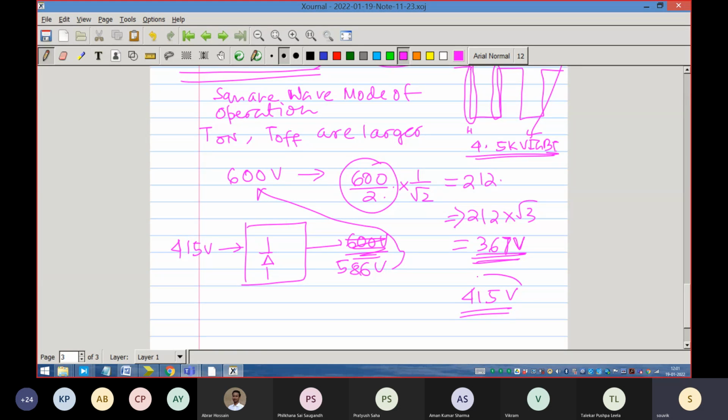But the machine is designed for 415 volt. So you are underutilizing the machine. You are not able to apply 415 volt to the machine. The machine is underfluxed because that is what you are able to do. So there is a natural tendency to increase the voltage and go to 415 volt. When you multiply by another factor, 4 by pi, which is the maximum over-modulation zone, how much is that?